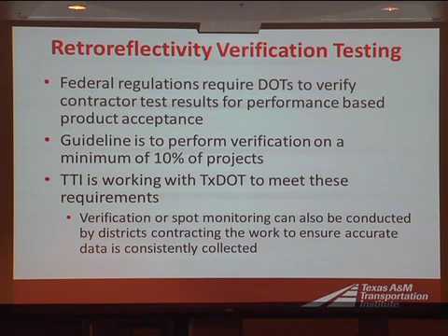So the retroreflectivity verification testing, what is it? Why are we doing it? Federal regulations require DOTs to verify contractor test results for performance-based product acceptance. Now, with the requirements to meet certain retroreflectivity levels on the pavement markings, TxDOT can't accept the work unless those performance values are met.